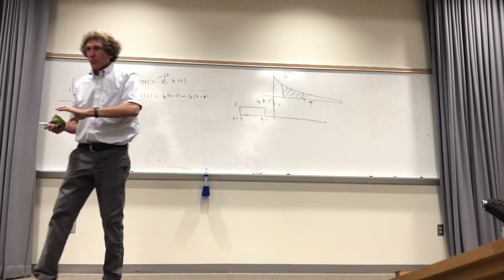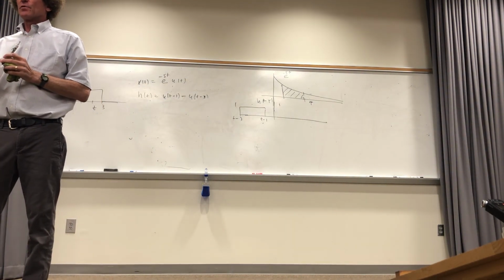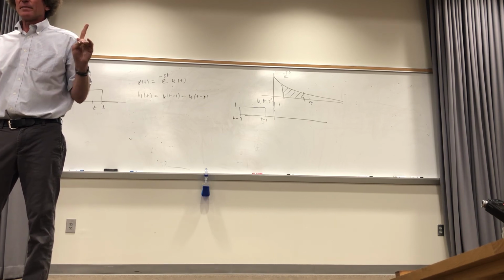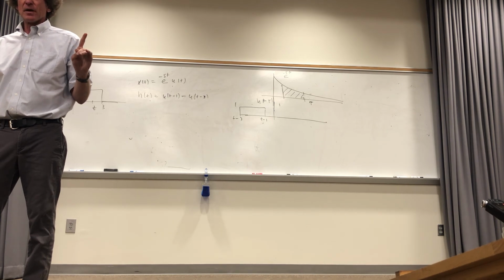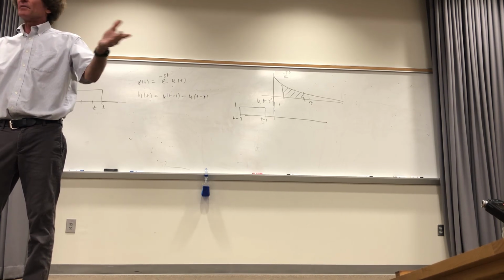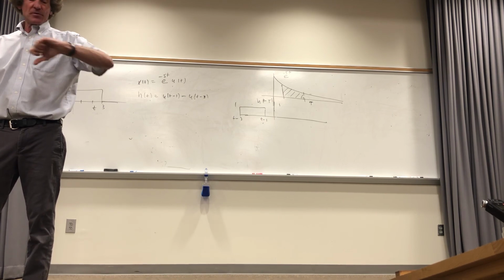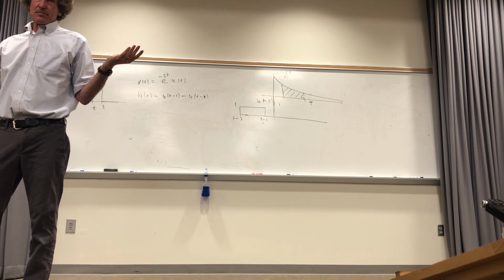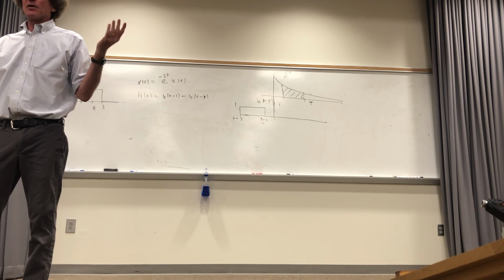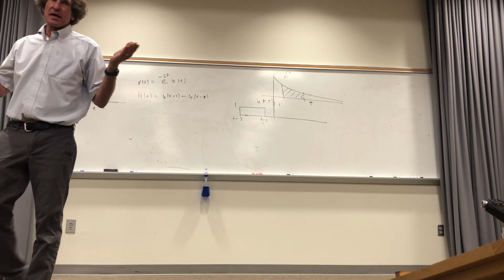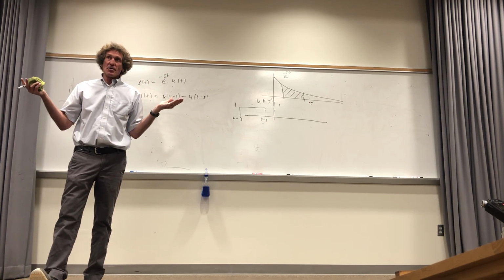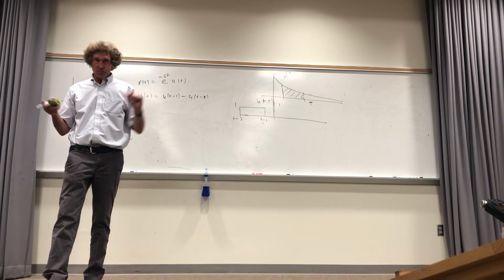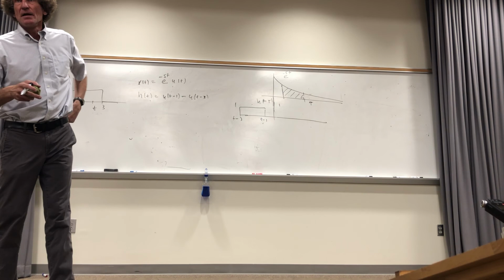One other point I'm going to make with Laplace transforms in realization. Remember to do partial fractions correctly. If you're going to do an inverse Laplace transform, partial fractions, we haven't done those in a while either, so make sure you know how to do them. If you have something you can factor, let's say you have something a over s, and then you have an s squared plus 3s plus 2, something like this. You know that factors into s plus 1, s plus 2, times s downstairs, and each one of those is a pole, and you have to calculate the values. All right, I think you know what I'm talking about.